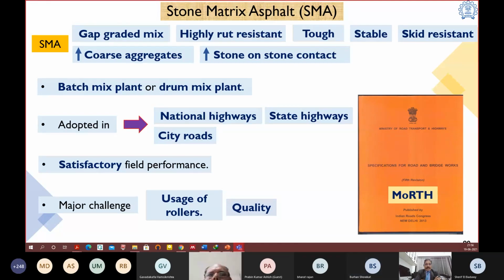First of all, the mix design, production, and also the compaction, and then how it is going to go into the field. And also the fiber plays a very critical role. What kind of fiber you are using, how you are adding the fibers, and what kind of plant you are using. All these things are very, very critical in using SMA. It is good, but if we don't have good paving practices, technology cannot help us. So just for the information of all international participants and Indian participants, we have been picking up SMA now in India. Hopefully it is going to be very successful in the coming years. Yes, thank you.